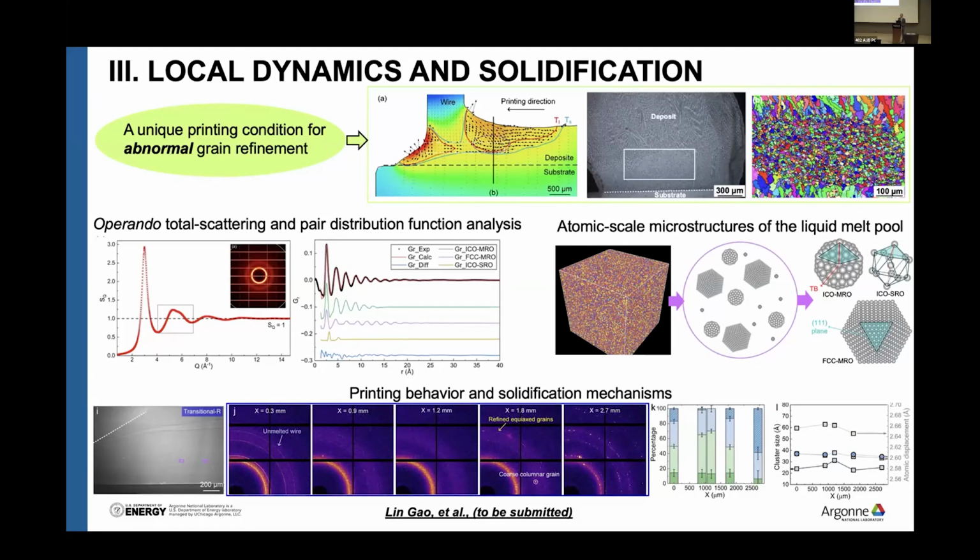Yes, but this is a very good concept. One potential of this work is that in our work we only adjusted the wobbling with a specific phase. We can further adjust the angle of the wobble and the path, which gives further freedom to tailor the crystallographic texture with a specific orientation. If we want 112 or 113, we can. That is our hope. This is my PhD work, and I really hope that new students can pick this up and do further research on it.